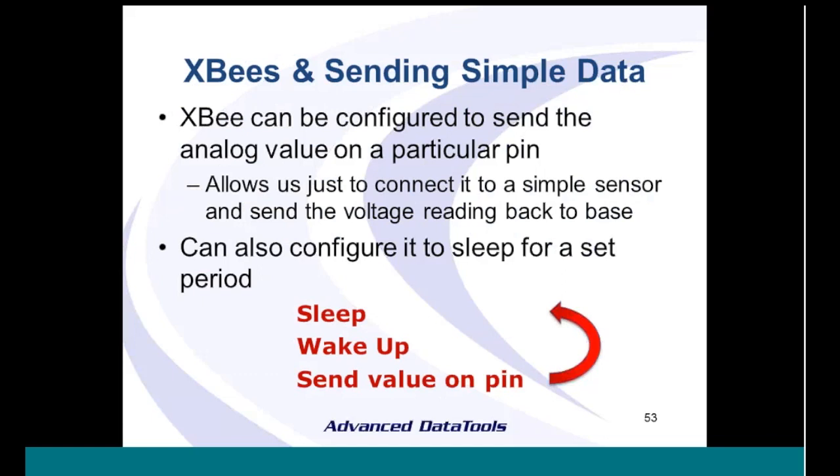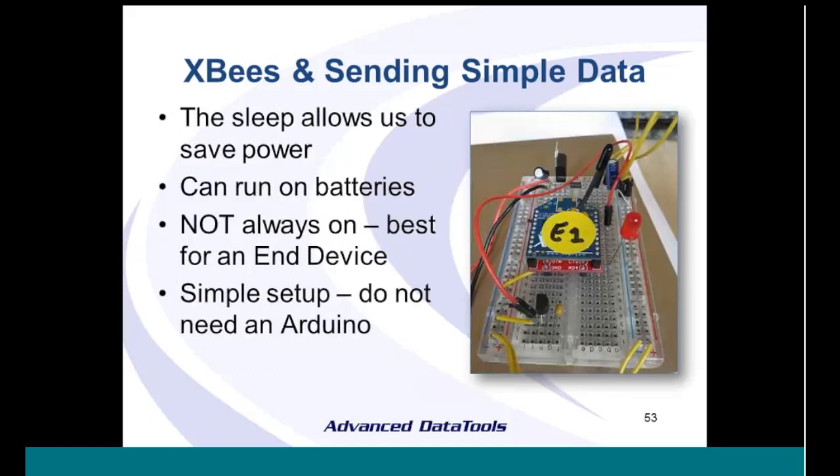So I've got a few of these. Here's an example of one of my prototypes, shall we say, where there's no Arduino involved. We're just powering the radio. And we've got a little temperature sensor on here. Just going to wake up, read the voltage, and send it. And then we'll interpret that voltage as a temperature on the gateway. So this is what we'd use for the end device on the edges of our mesh network.